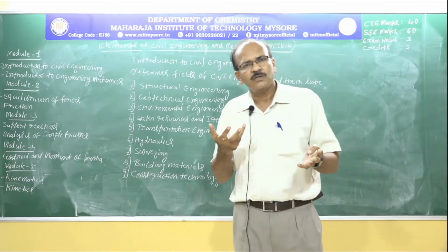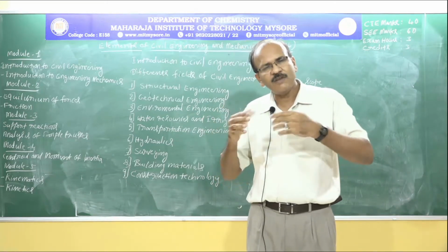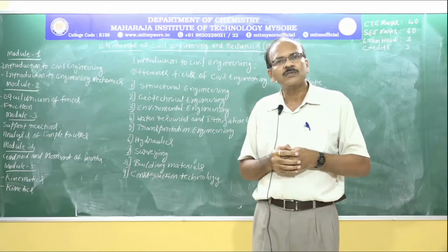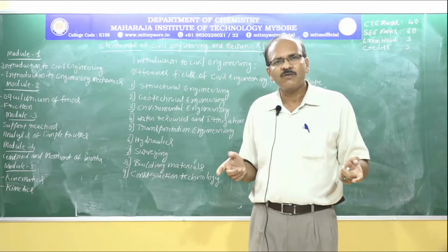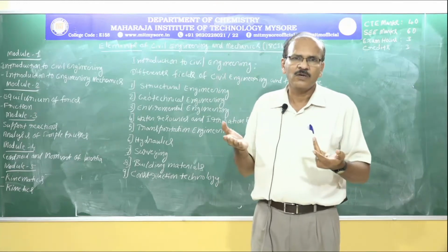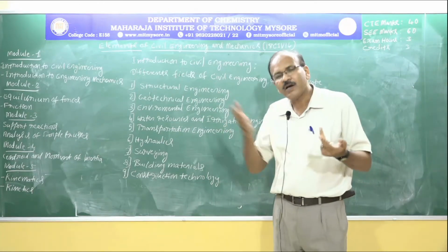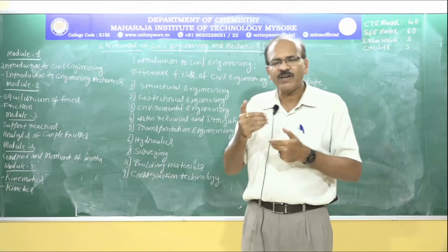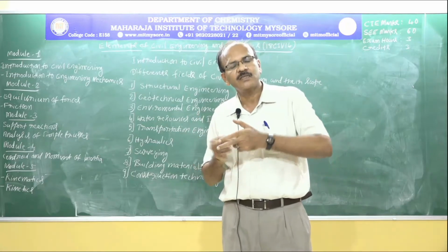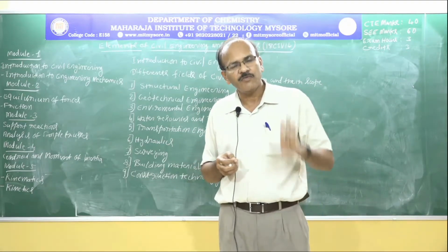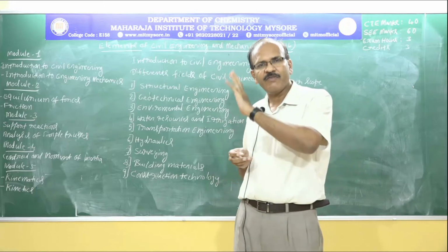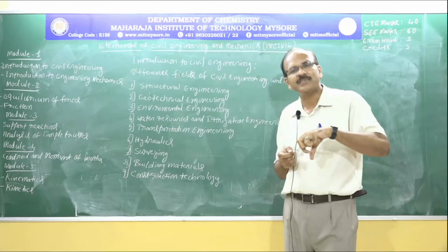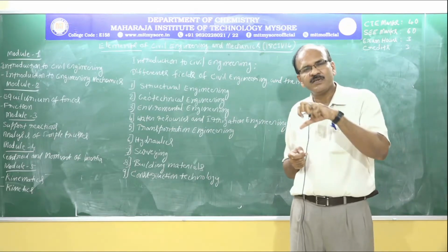What are the dead loads? Dead loads are the permanent loads, like the self weight of the structural components or bridge elements and the road surfaces. What are the live loads? Vehicle loads. So vehicle loads are the live loads coming on a bridge. Including the impact effect, we take that into consideration, because the loads will be moving and we apply brakes and we accelerate a vehicle.